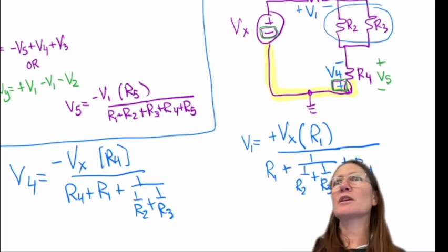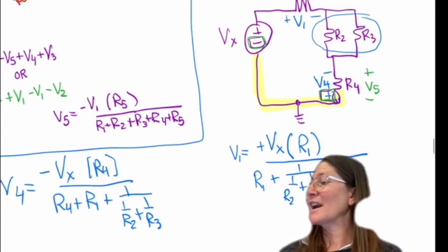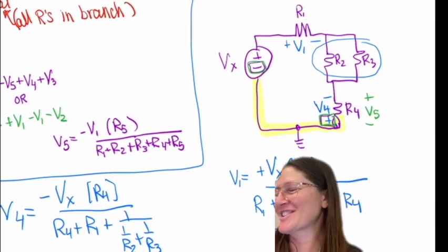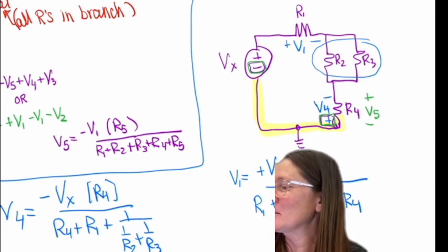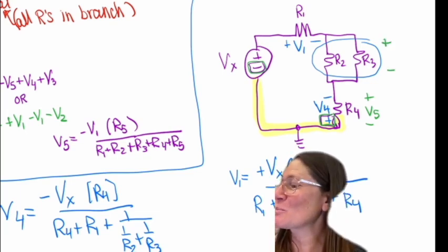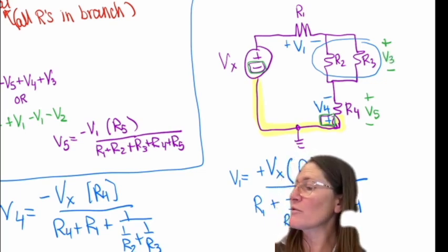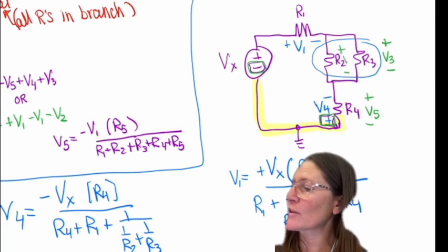All right, yes. What if you wanted to find a voltage drop across like R3? Okay, that was gonna be my next one, so good question. So, somebody tell me polarity on the top arbitrarily. Okay, if it was positive to negative, and I called this V3, note that V3 is also across V2.